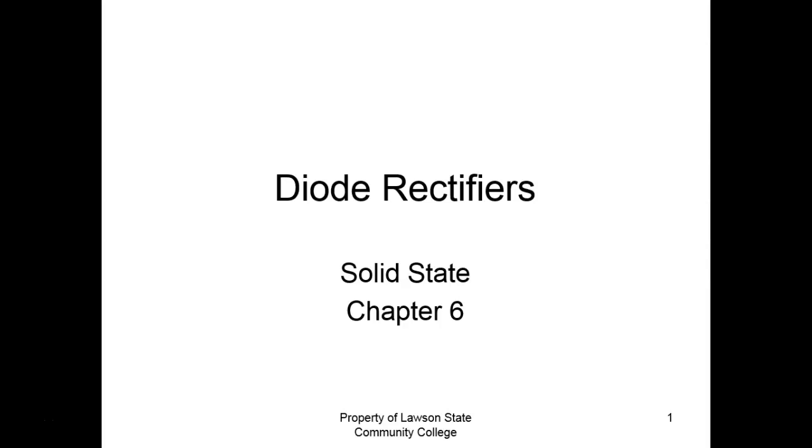So what we're going to do here, and this is going to be the first lab we're going to do, is we're going to let y'all check a diode. Everybody okay on how to check a diode? We still call it an ohm meter, but it has a diode scale, right? You understand that? What the diode scale does is it actually shows you the voltage the ohm meter would have to put out to cause the current flow. So it's really, really neat.